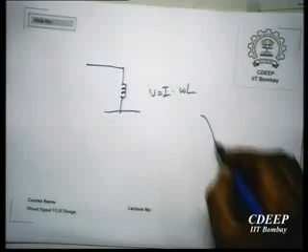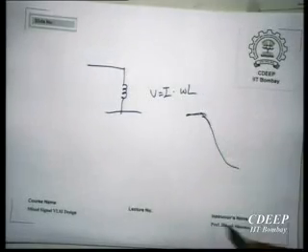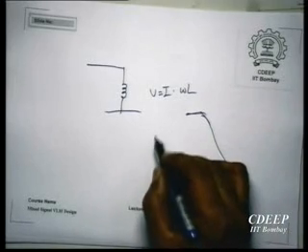So in short, if you know the transfer function of your line, then suppose you have a transmitter whose transfer function is the opposite, then between the transmitter and the line you will pass high frequencies properly and you will receive the signal at full amplitude. Okay, so what do I need? If the output is like this, assume that we treat it like a single RC. Okay, this is frequency, this is response, right?